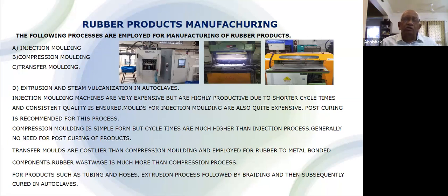So why I am insisting on this injection molding machine is here everything is preset. What you see on this screen, I have to enter and keep it forever. So no changes will be made by the operator or anybody. And the process that this follows is totally automatic. You don't have to do anything. The job of the operator is just to remove the part and keep it.